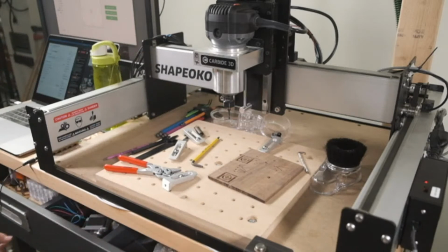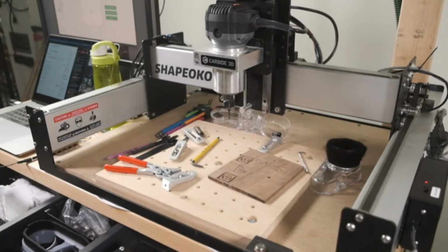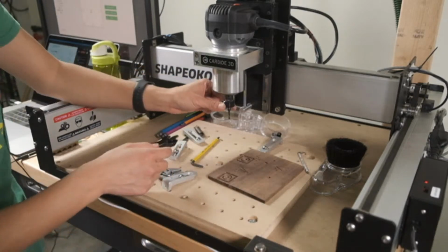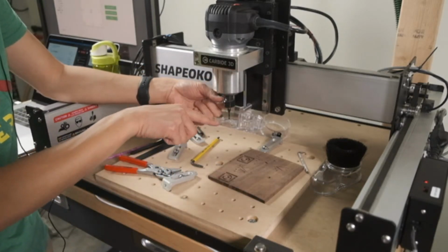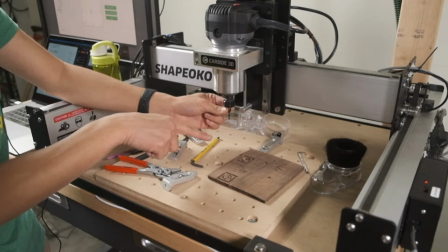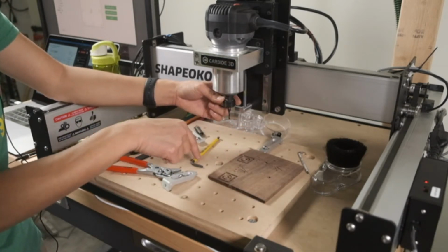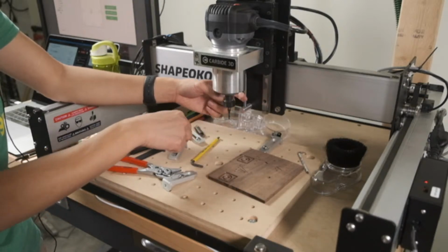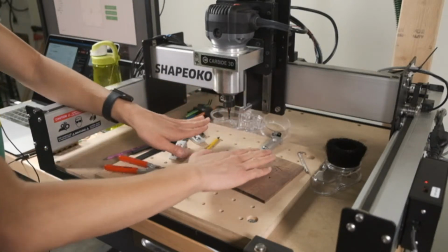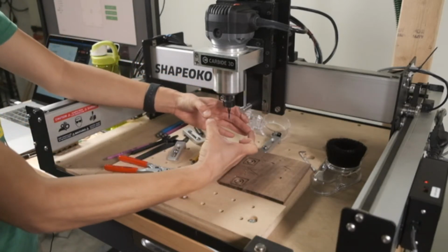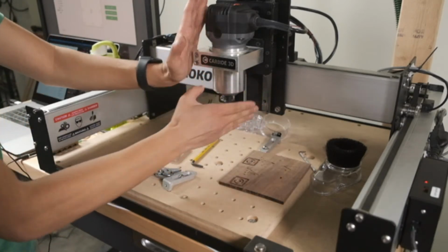Let me see if I have one here. I don't think I do. But basically, you can even take a coat hanger and just bend it from the spindle nose to the table and just spin it. You're looking for a conical swept area to tell you which side of that swept area is closer to the table or not. If it's low on one side, that means your spindle is crooked this way.